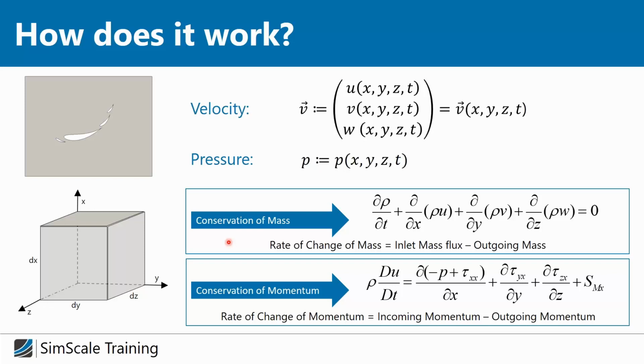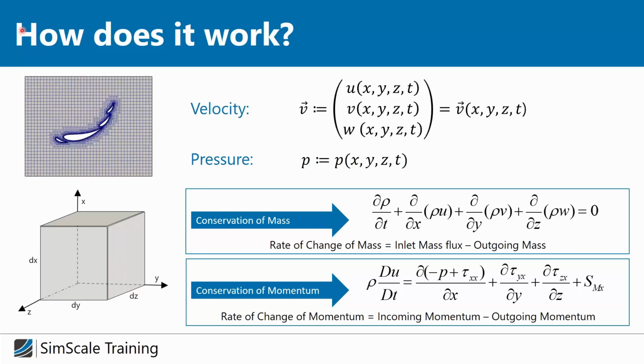And that's basically what we do in CFD. It's about calculating what is happening inside this element. So we cannot apply this equation on this complex model, but on a simple one. So what do we do? We will just represent our complex problem and assemble it by a lot of small, simple elements which we can calculate. And that's basically the idea of CFD.